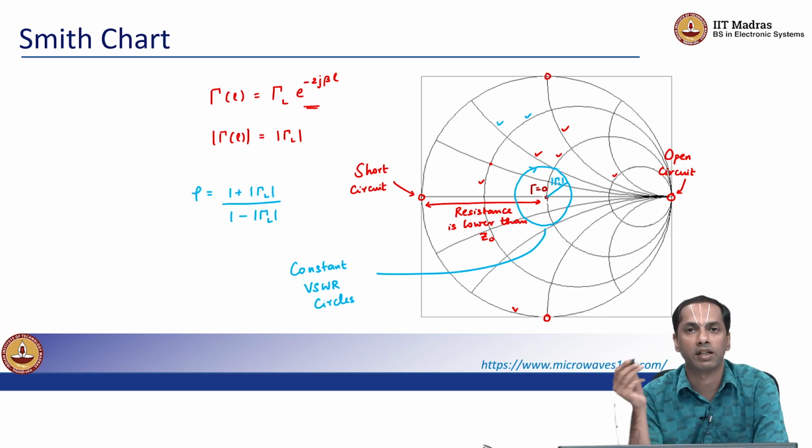So I just have a floating or an open transmission line, but to be able to denote that on a plot is very difficult because the point infinity is very hard to draw. But doing this transformation allows us to look at any load that you might have, because all the points in the right half plane condense into points within this unit circle. So it is very convenient for us to study all loads in a single plot.